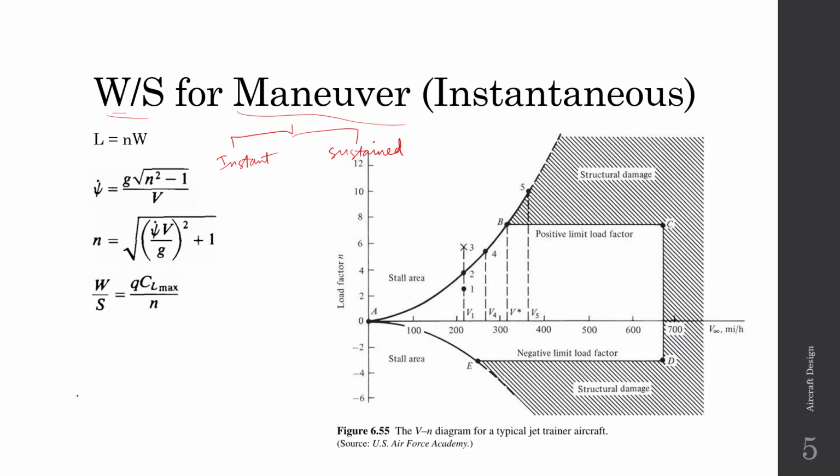So if I draw a forward view of the aircraft, you can consider an aircraft like this, with the wings and the tail. Normally it flies like this and the lift and weight are balanced, but when the aircraft is turning, the lift vector is pointed off to the side, but the weight obviously still acts downwards. So this offset lift vector causes the turn. Now if the turn is not properly managed, then the aircraft loses altitude and velocity when it is turning.